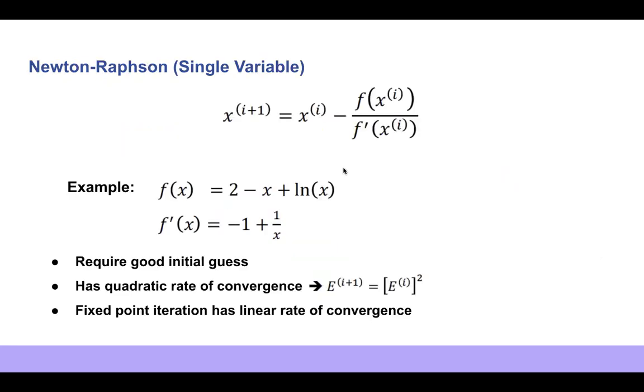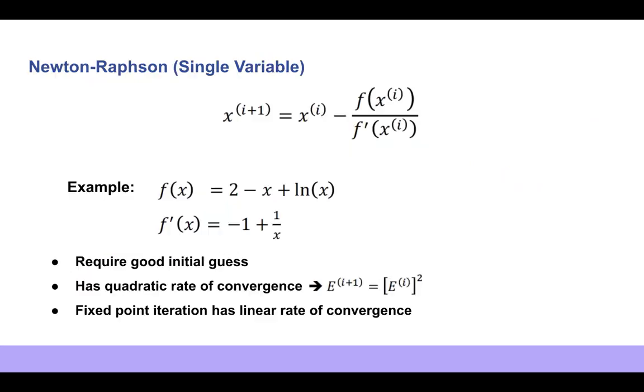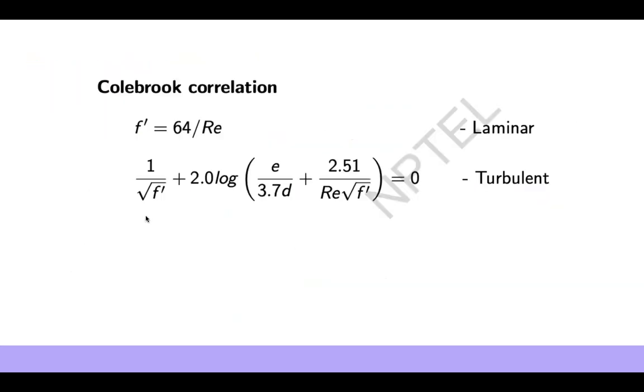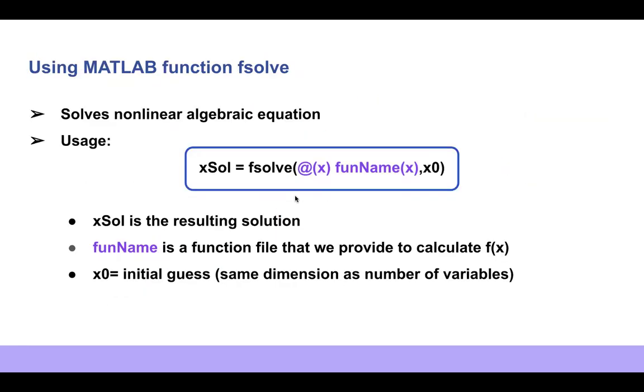Okay, basically, the first one that we'll be seeing is fsolve. Okay, fsolve is the one that has been used in the recorded lectures. And apart from this, we'll try one more solver, which is fzero. Okay, now next is fsolve. Basically, it's a MATLAB inbuilt function, so it solves nonlinear algebraic equations. The equation that we have right now, if you go back, you'll understand that this is a nonlinear algebraic equation. This is a nonlinear function. So this fsolve exactly does that. It solves nonlinear algebraic equations.